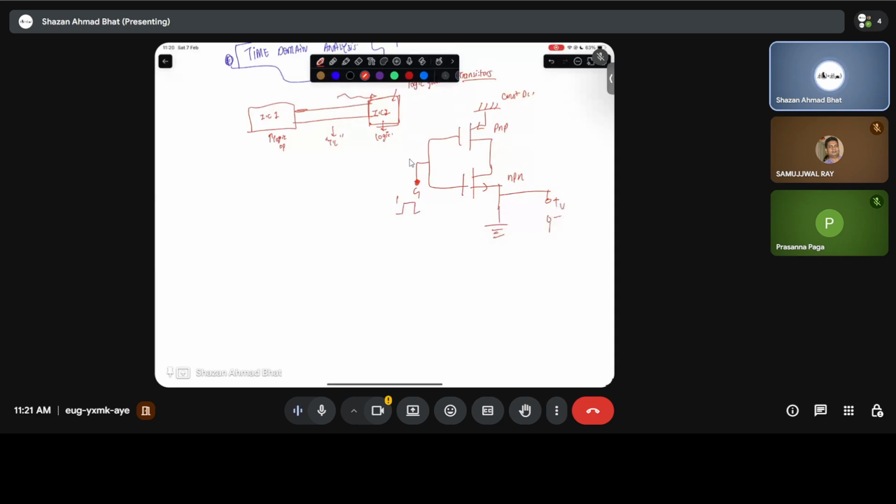But the essential thing is that the response is not exactly abrupt. You don't get the abrupt response. Let's say for example you give certain voltage, and this 1 and 0 is nothing but a certain voltage level, 5 volt. Now you will say, what is this 0 volt? You cannot measure 0 volt, but the 0 is actually some threshold voltage. If it goes below some threshold voltage, then that is basically read as 0.